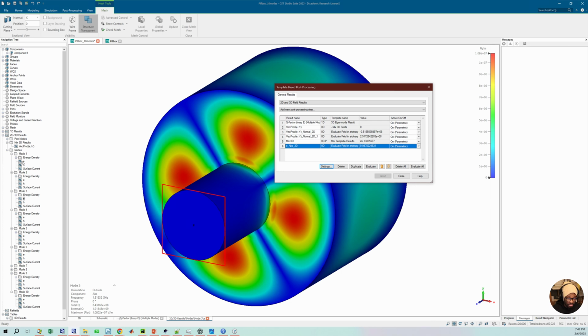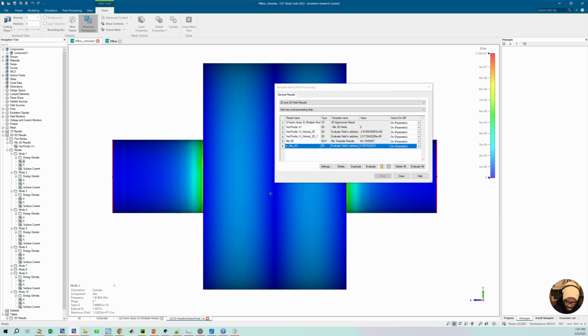I said that for modes that are strongly trapped, strongly resonating inside the cavity, I do not really trust the external quality factor calculated using any of the methods. I haven't benchmarked this to see which one gives a really good result, but from my experience, the quality factors of such modes are highly mesh dependent. If your mesh changes slightly, then the quality factor gets different.